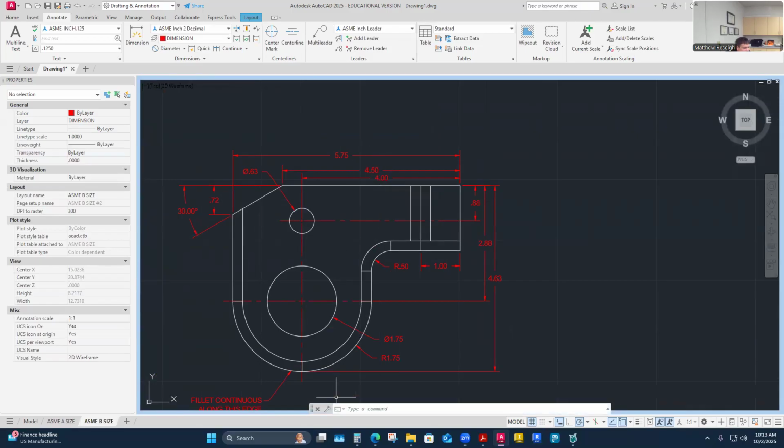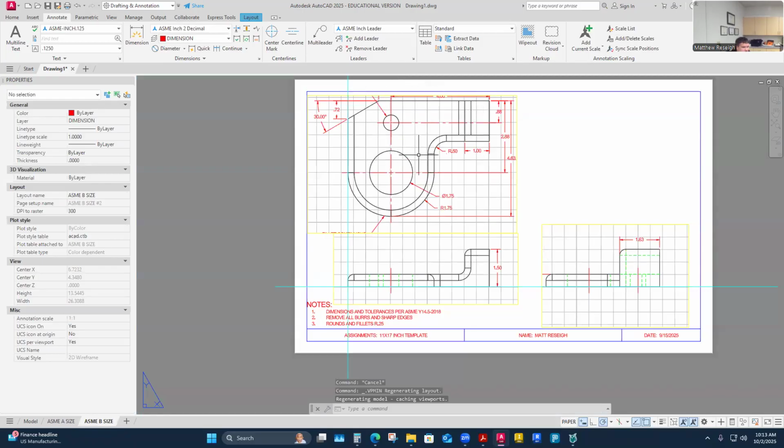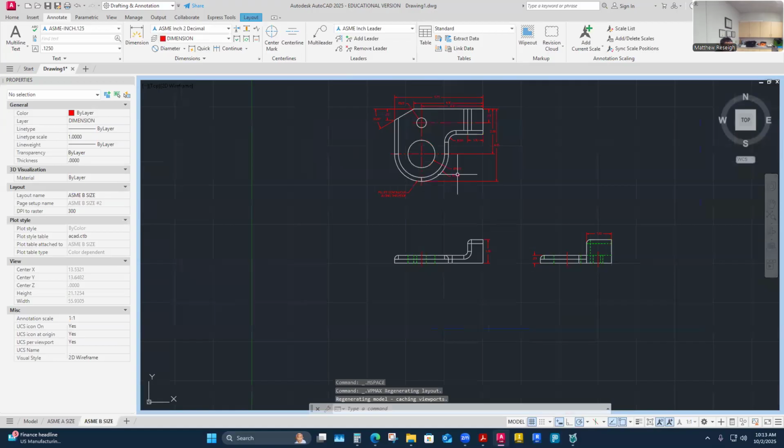I'm being a little strategic because I know on my drawing, if I jump back out, I'm a bit crowded here and I'm going to have to move this view down and resize my viewport. So I'm probably happy keeping my upper dimensions as compact and tight as I can. That was always in the back of my mind, that I've got limited space above it. However, because I didn't put very many dimensions in the front view, I'll be able to pull down my viewport from the front view because it's not really carrying any dimensions. So I'll clean that up once I space them out here.